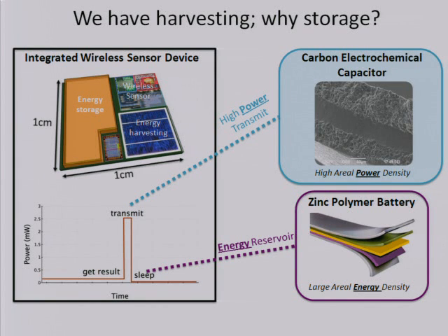There'll be a period when it will want to get results, and typically it doesn't need to transmit those results all the time. So there's a brief period, which might be microseconds or milliseconds, when it does transmit that data using the radio, and for that there's a lot of power required, something of the order of a couple, 3 milliwatts. And then typically the device might go back to sleep for a while.